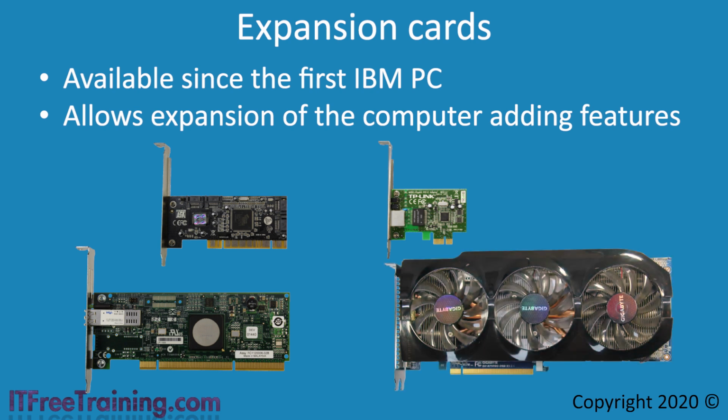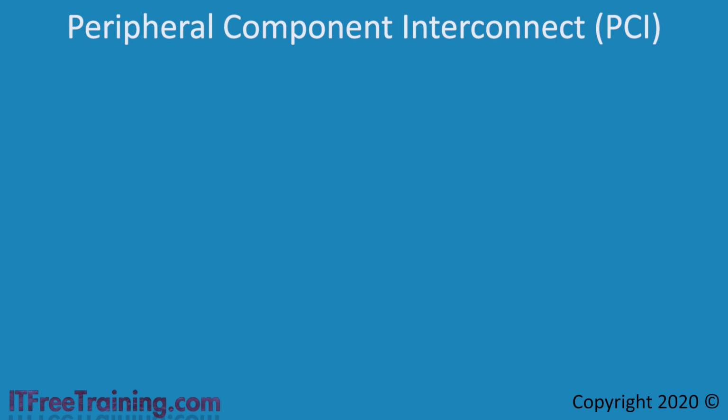Many high-performing video cards on the market will be quite large, like the one shown here. If you are installing a large expansion card, make sure that it will fit into your computer case. I once had to remove part of the computer case with a hacksaw to get a large graphic card to fit into the computer case.